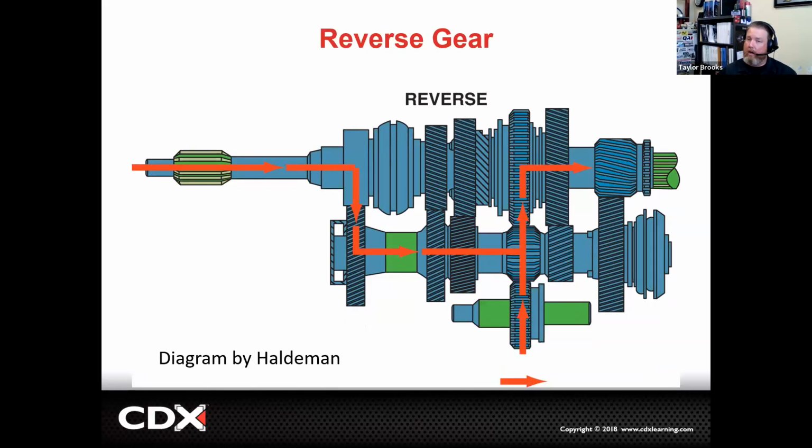Now, reverse gear on this particular transmission that we have as a cutaway is not synchronized, meaning that none of the three synchronizers that we're going to be using will be used to bring the shafts up to speed. It will be a straight cut or spur cut design, meaning that we have to have the vehicle stationary to be able to smoothly shift into first or reverse gear.